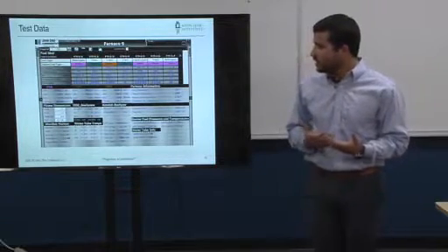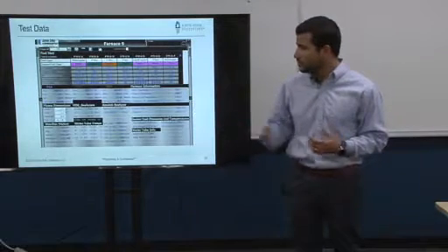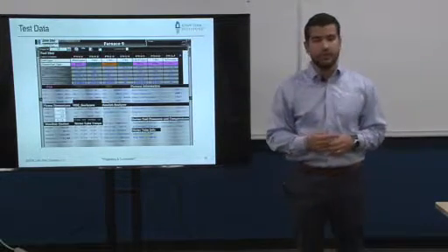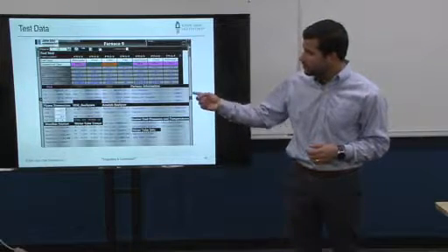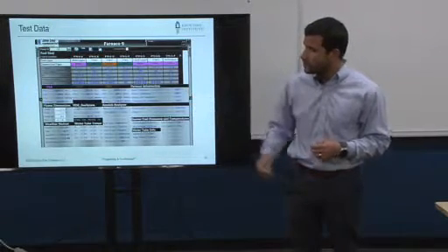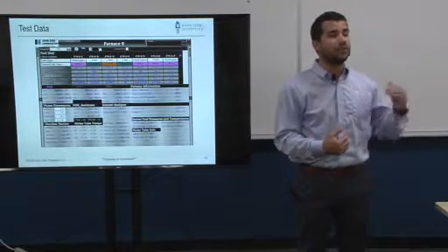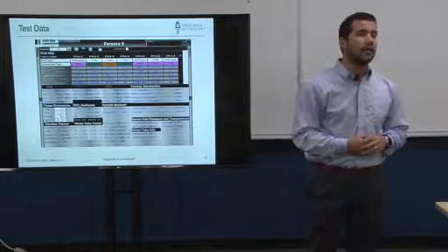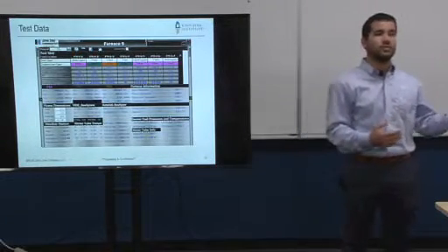But there's other data here that we also look at, right? Other than measuring fuel flow, we also measure airflow through the burner, and that's where you see the burner pressure drop. We also measure a couple of temperatures: the furnace temperature, the stack temperature, and the floor, or the temperature at burner level. Those are really important when you are comparing to your customer's facility.